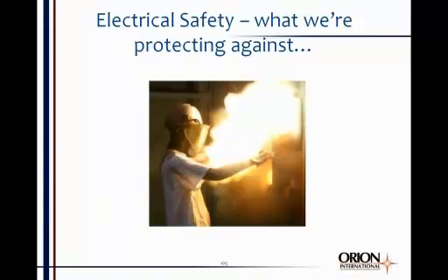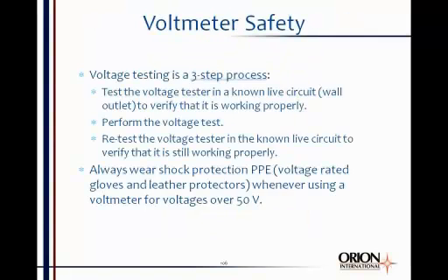And here's another arc flash event. See the heat and the plasma coming out, hitting the guy right in the chest. He's got on a cotton T-shirt. He does have a face shield on, but it's not an arc-rated face shield, so more than likely this non-arc-rated face shield is going to melt and burn. His T-shirt will catch on fire, and he'll have vast body burns. He may not even survive.